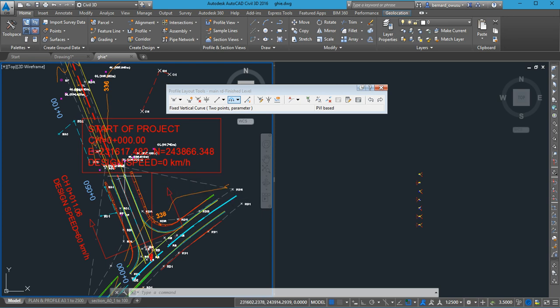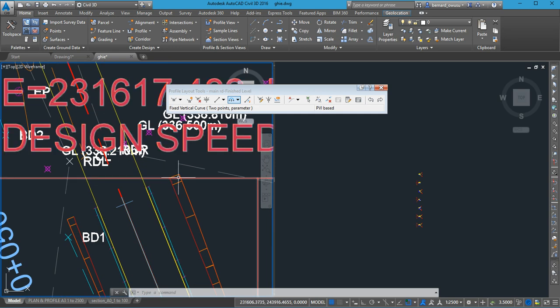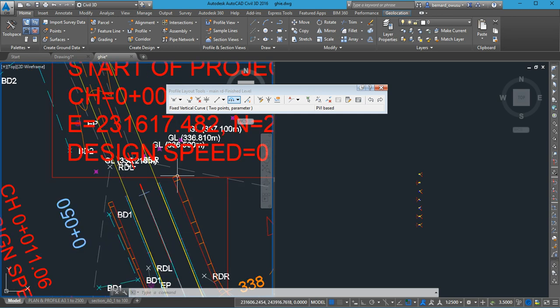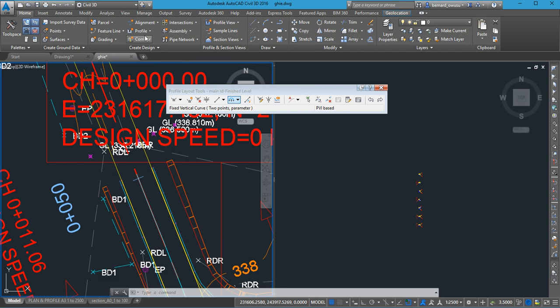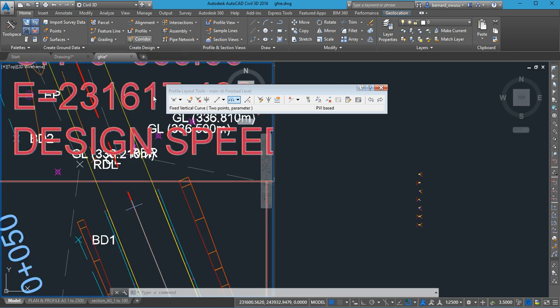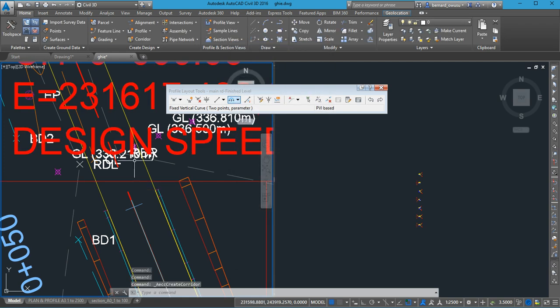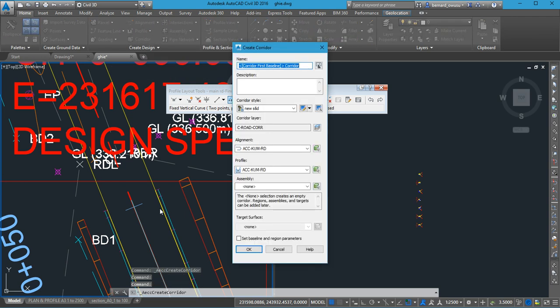Okay, so we are going to insert corridor from here, starting from where this corridor ended, all the way to the end. So please look up. This is how we insert the corridor. Do you see corridor here? So select corridor. Have you selected corridor? You go up here, corridor. Have you selected it? Then when it comes, you can give it a name. Then the code style, we leave it as it is.